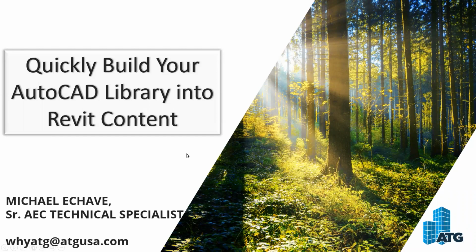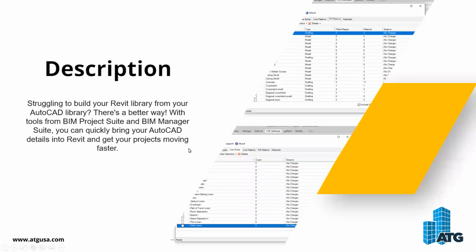All right, so next, we're going to be talking about struggling to get our AutoCAD library into Revit, and some of the quick ways we can do this. Specifically, I'm going to talk around two tools. One is from the BIM Manager Suite, which is a free tool. It is called Detail Link. The other tool is also from the BIM Manager Suite, a paid-for tool, and that one is Type Swapper. We're going to go through how to use both of those tools.